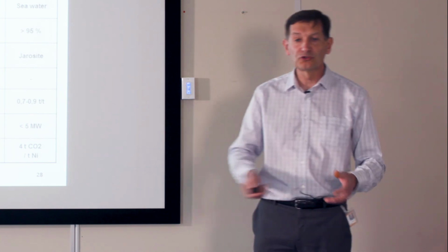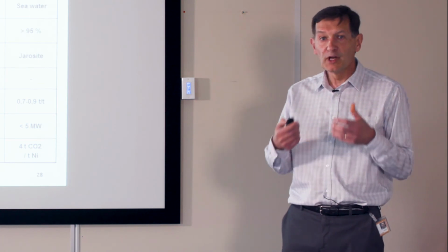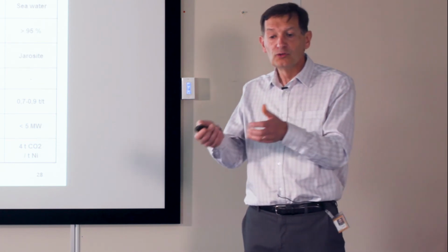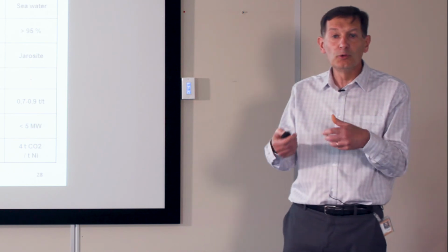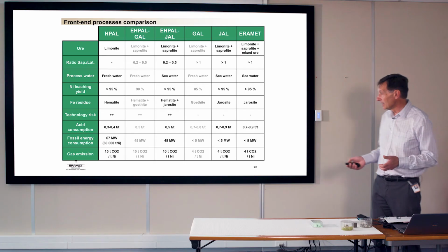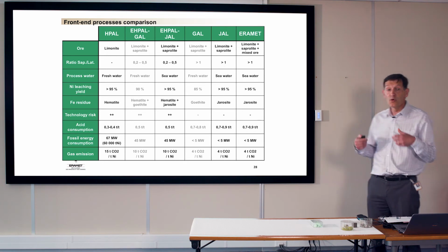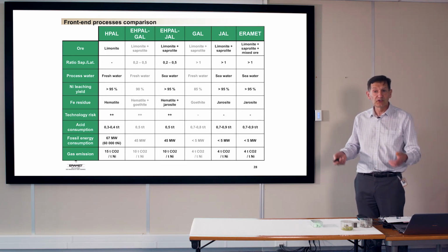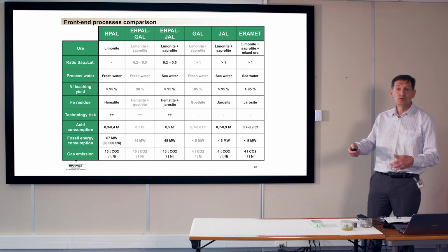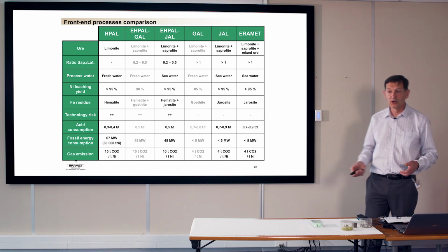There is a lot of sulfur available in the world, and when you burn the sulfur to create acid, you create energy, and you can recover this energy. When you recover this energy, you have all the energy needed for the process, to heat the equipment, to have electricity for the pumps, for the stirrer, and so on.